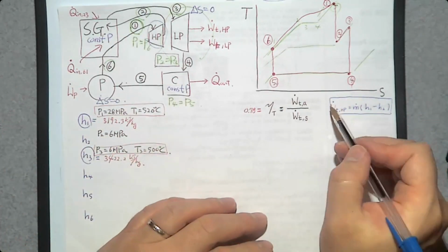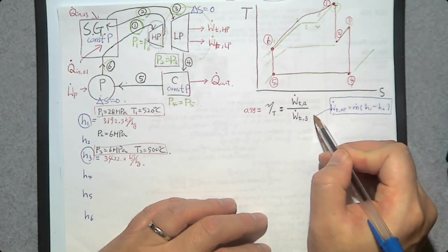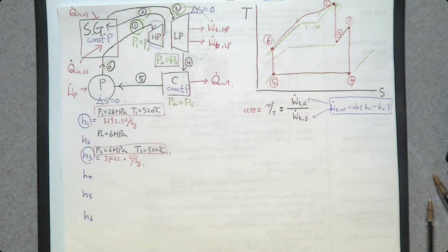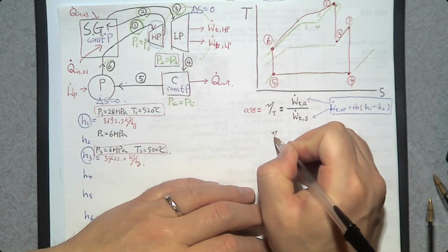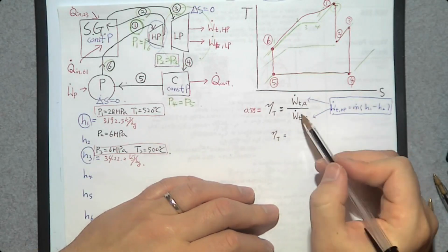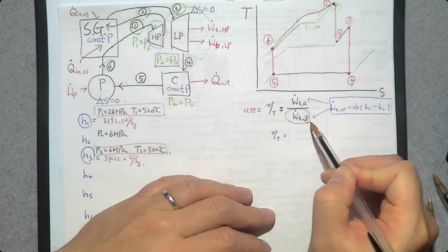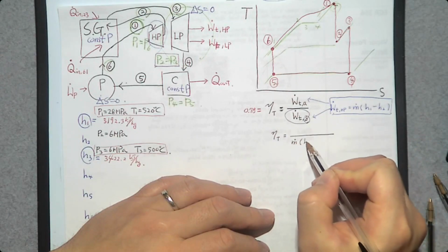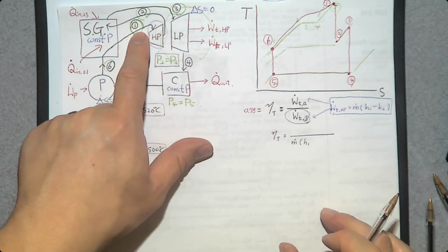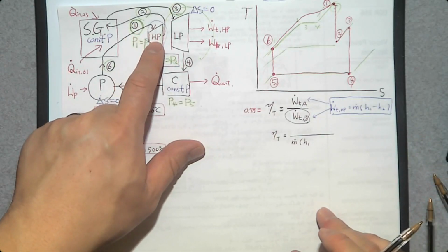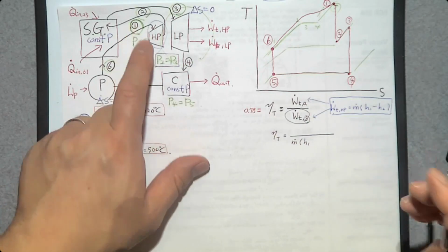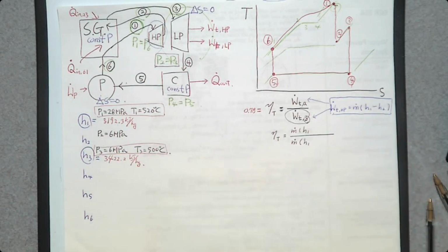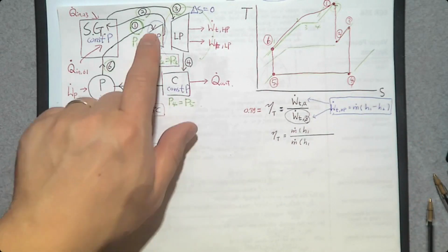Now we need to think how we can apply this for the denominator and for the numerator. The turbine power produced by the ideal turbine can be determined by m dot times H1. H1 is the inlet condition. So regardless of the turbine, H1 should be the same between the isentropic turbine or the actual turbine, because this H1 is before entering the turbine, right?